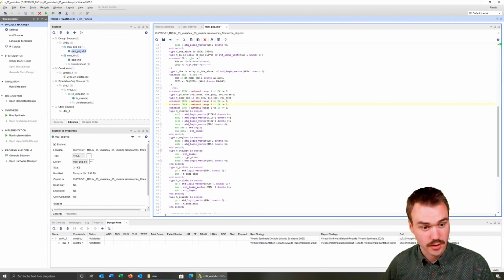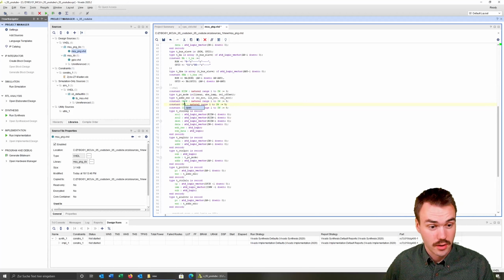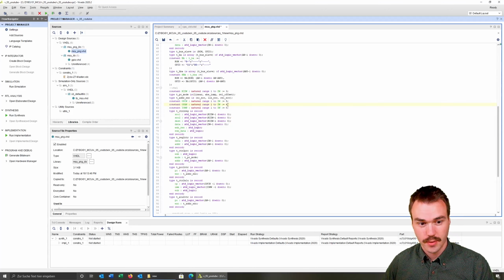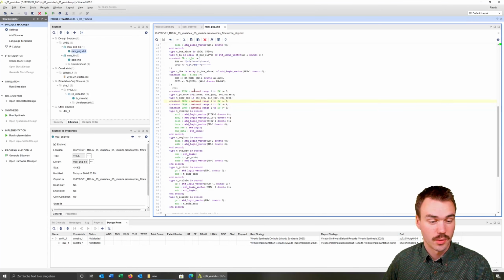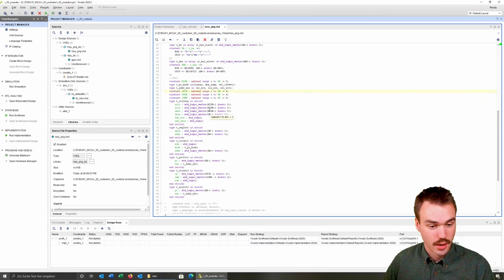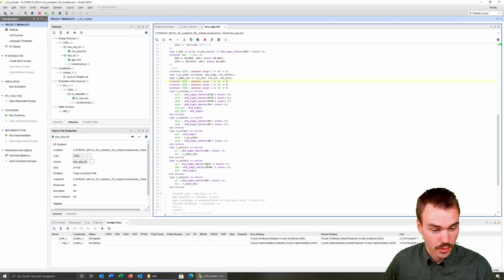So let's define here a new constant, ALU operation word width, and we can say this is 4, because the first bit is only for other instructions like memory access or memory write back. So let's change this here, operation address width.